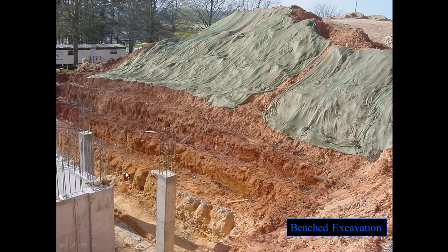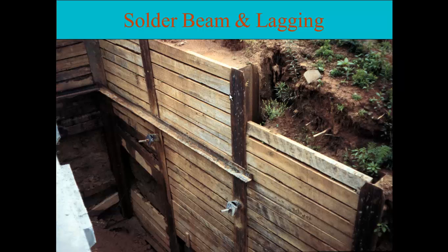You can see they've dug this site in benched areas and piled some of this material up with some plastic to keep it from eroding, so somebody can work around this foundation. They don't have to worry about the sides caving in. If they've just dug this down straight, there's a good chance with a good rainstorm or just natural ability to hold its shape, it could cave in. So you have to do this benched excavation.